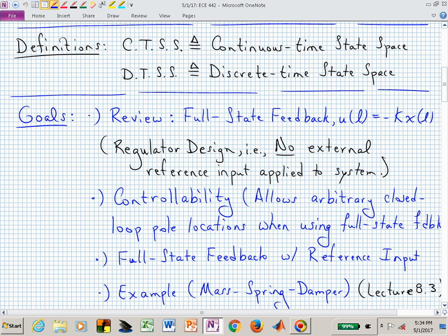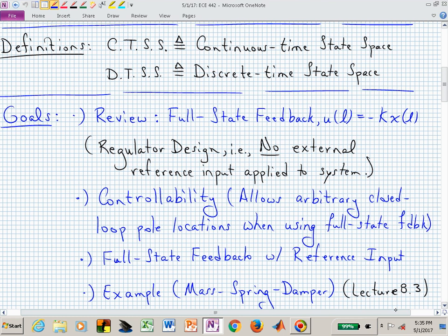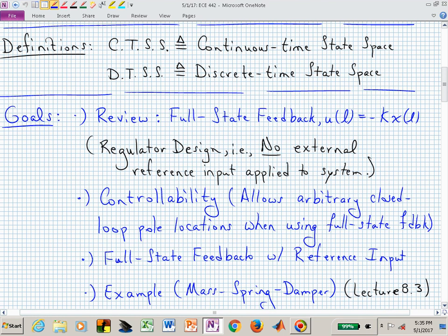We'll then talk about when is it actually possible to perform full state feedback or to make this assignment of closed loop poles anywhere we want in the z-plane, and obviously you probably want those to be inside the unit circle, and you know that you have the target or the circle, you have the heart, and you have the wedges to inform where you place your dominant poles.